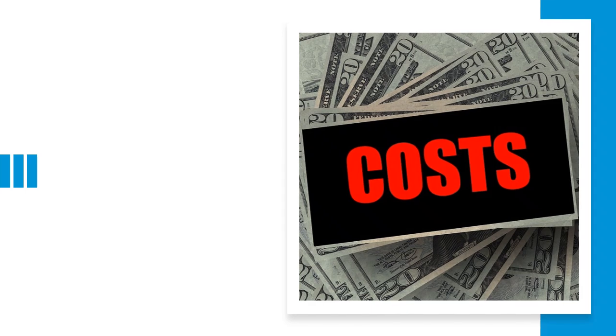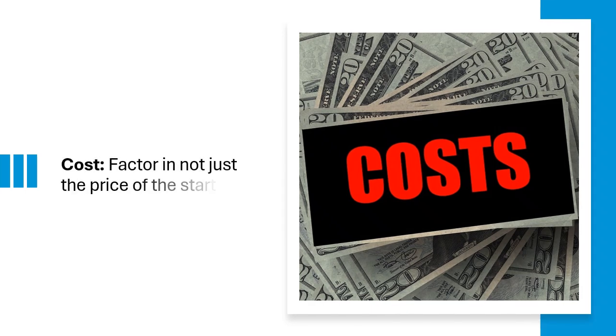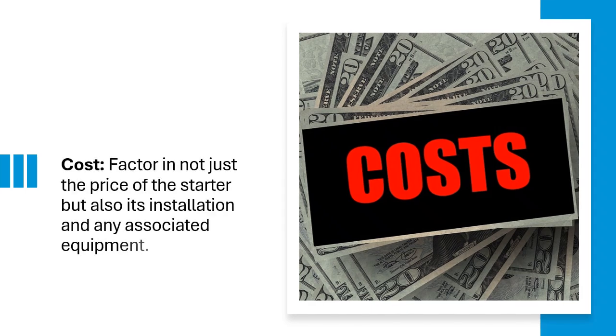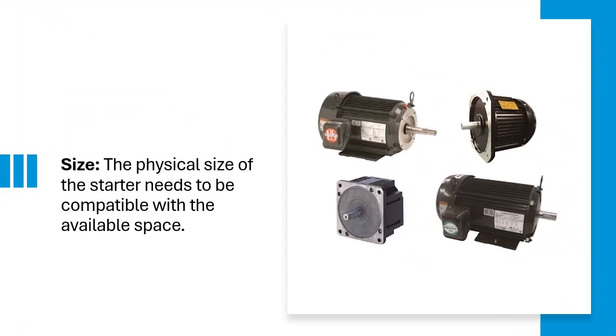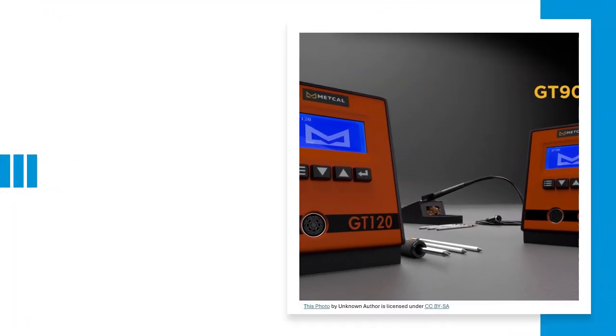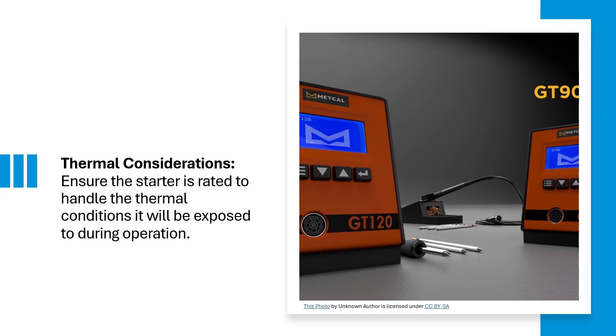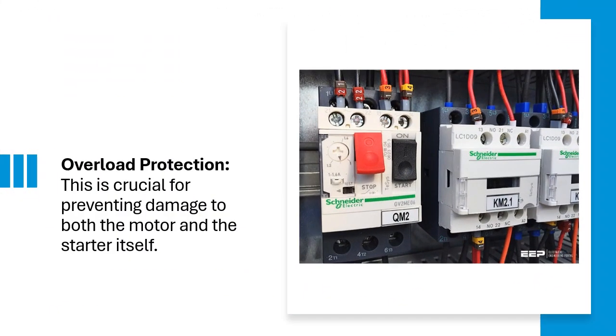Cost. Factor in not just the price of the starter but also its installation and any associated equipment. Size. The physical size of the starter needs to be compatible with the available space. Thermal considerations. Ensure the starter is rated to handle the thermal conditions it will be exposed to during operation. Overload protection. This is crucial for preventing damage to both the motor and the starter itself.